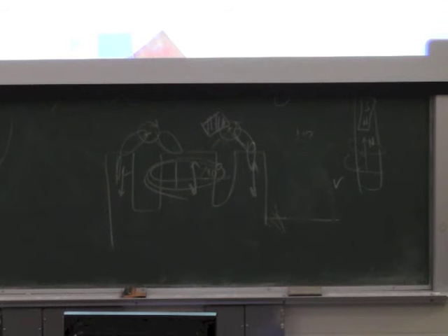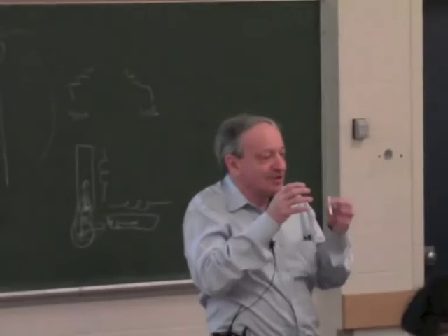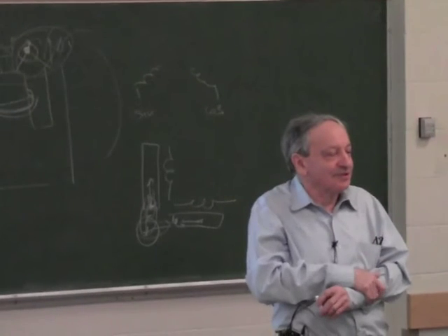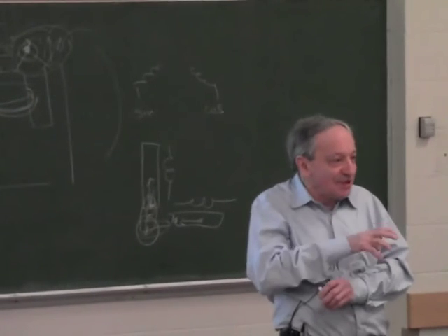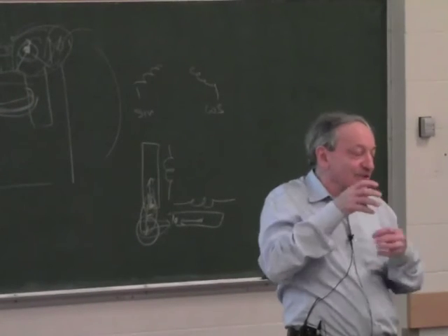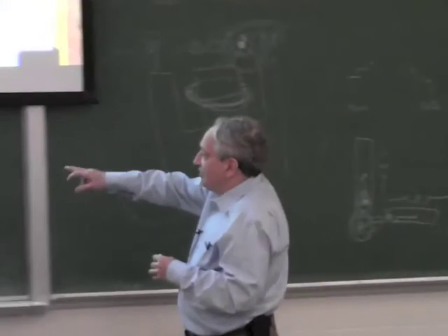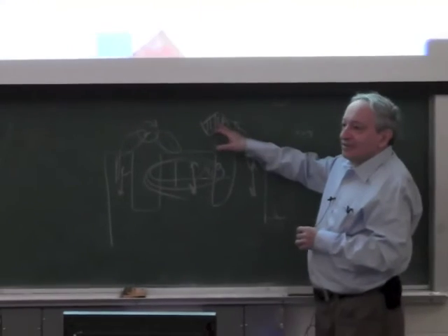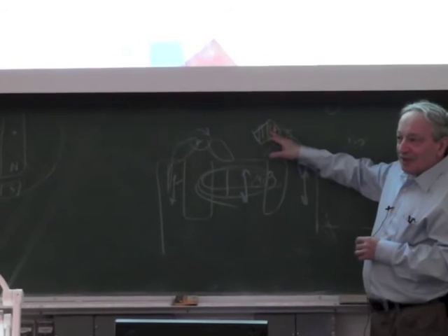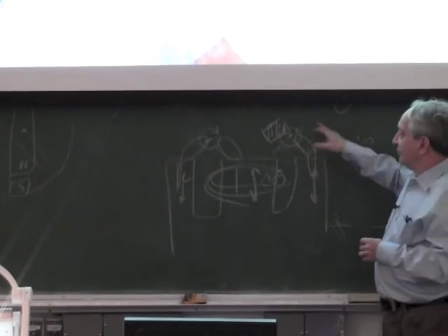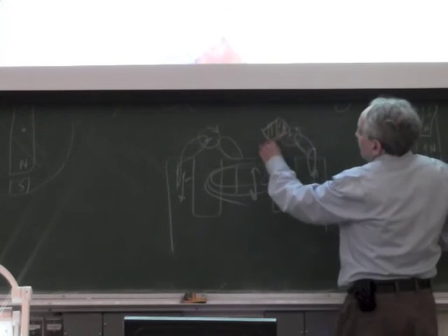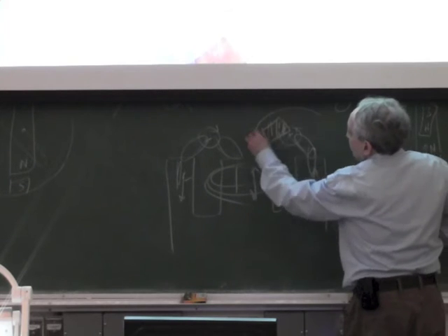Just don't be shy. You've seen an induction motor. It has something inside the rotating field. What happens to the armature when you turn on the rotating field? It rotates, right? Because of Lenz's law, we just went through it, it rotates. So what happens here to this piece? It's trying to rotate with the field. So this piece of conductor is trying to rotate with the field.